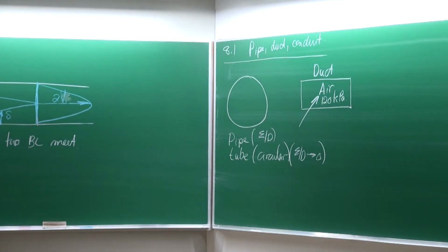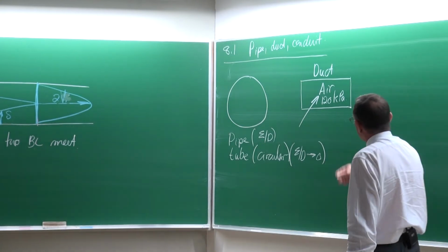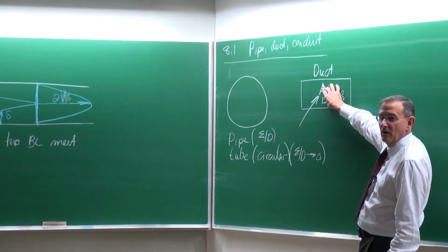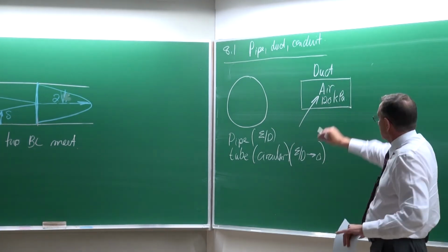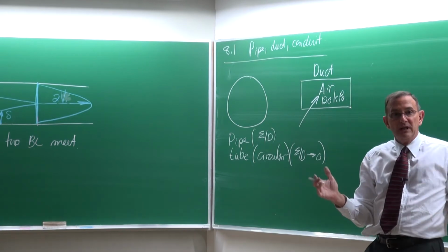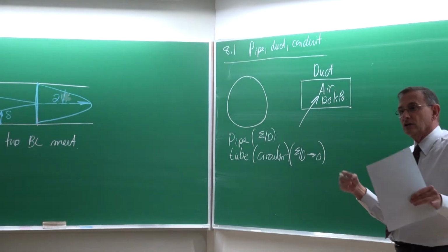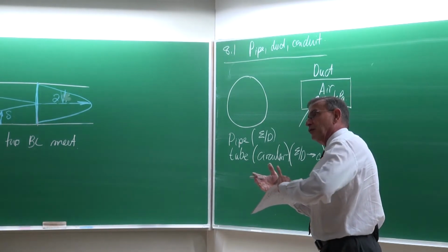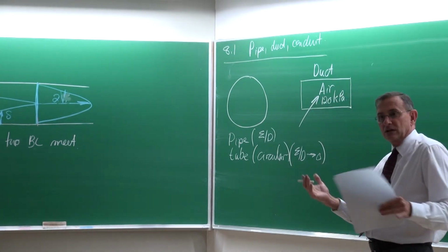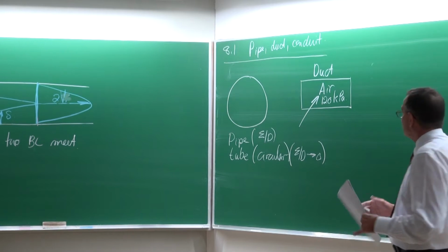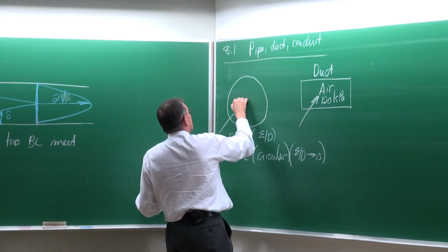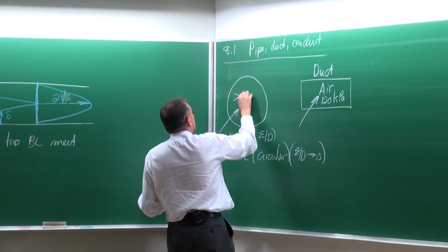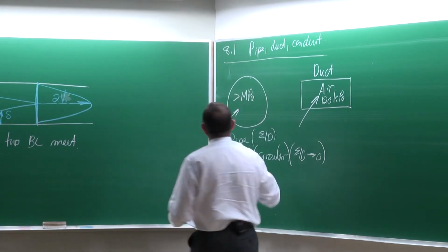However, they normally carry air, and the pressures in them are normally a maximum of 120 kPa. So they cannot take large pressure differences. If this pressure is becoming higher and higher relative to that of the atmosphere, then there's a huge pressure difference. There's a huge area normally involved, and if you keep on increasing the pressure, it increases lots of stresses and strains. With a pipe, however, in most cases, the pressures can go up to megapascals and even more.